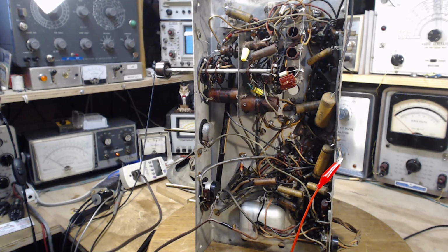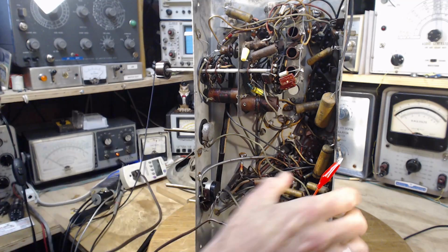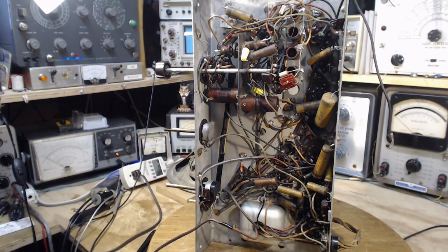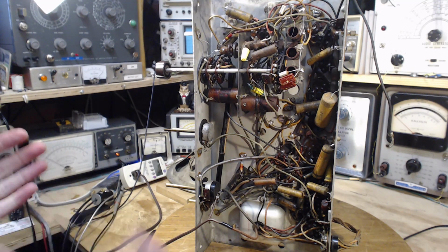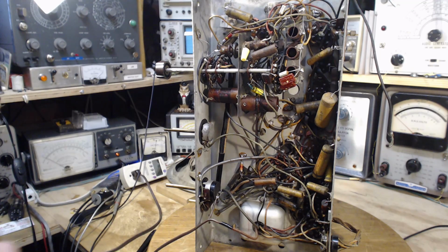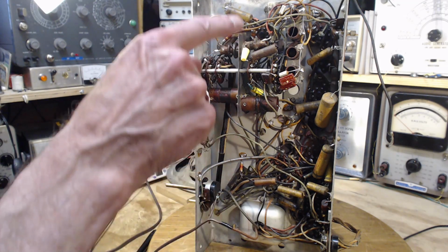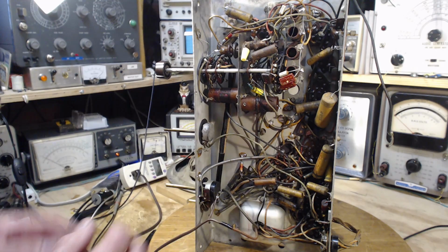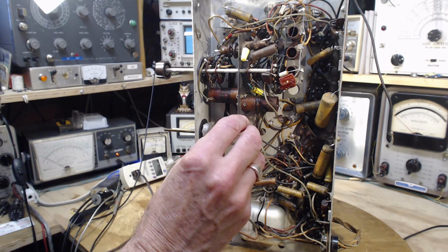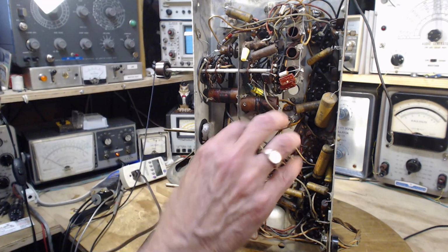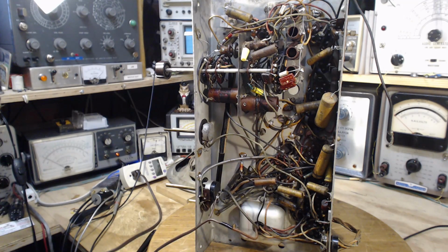Okay, I think we're at about the half-hour mark on the video that I'm preparing for this, so there's some more time. Why don't we go another step? What appears to me to be the case from a couple of observations is that the local oscillator is very weak on the C band. The C band is the shortwave band that covers a big range of frequencies. The other three cover a very small range of frequencies spread out on the dial for convenience in tuning. So on the C band, you're turning the tuning knob like this to tune stuff in, but on the other bands, which are band spread, you can be doing this. It's much easier to tune in on the band spread bands, but the C band is the one that appears low.